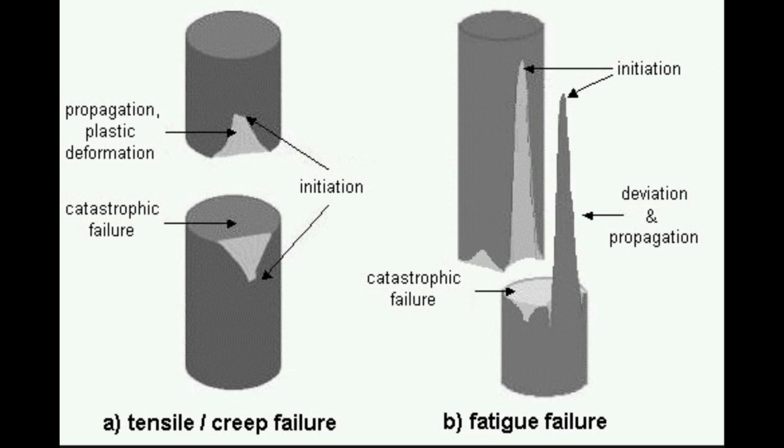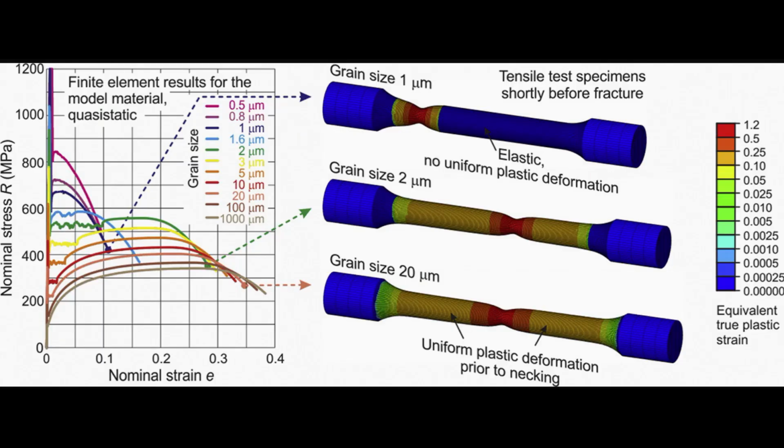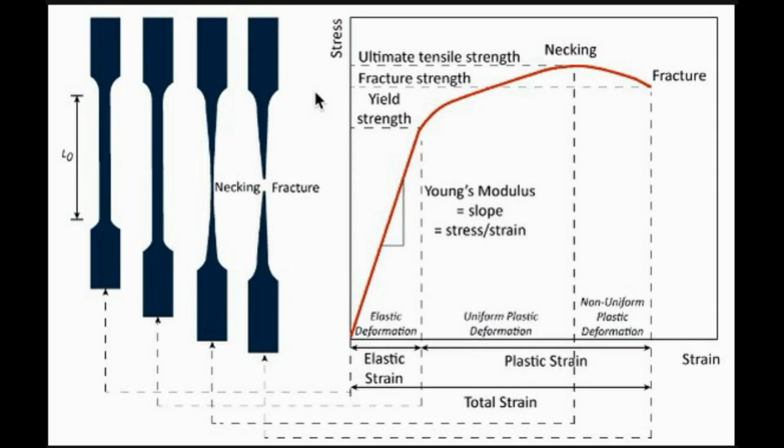It's worth noting that the specific failure mechanisms and modes depend on the material properties, loading conditions, and the structural configuration. Thinning is often associated with plastic deformation, while major in-plane stress failure can manifest in various ways, including yielding, fracture, or structural instability, depending on the material's behavior under stress. In engineering simulations and analyses, understanding these failure modes is crucial for predicting and preventing structural failures in various applications, such as metal forming processes, design of components under load, and the overall integrity of structures.